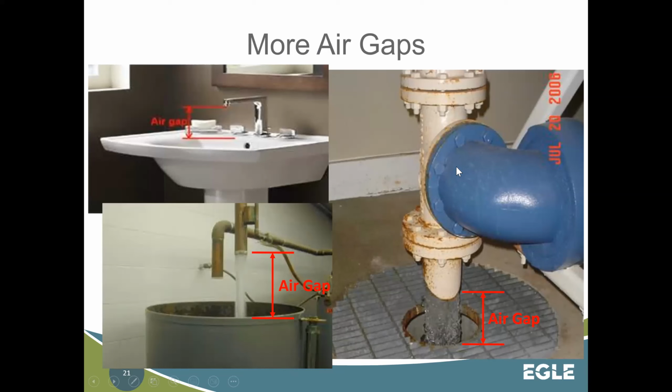And then here's an air gap to a drainage basin that you see typically in commercial sinks in commercial kitchens. And you can see that this one's cut at an angle. And we typically recommend, if you can, cut the pipe at an angle, because it doesn't allow the water to create that mushroom effect off the bottom. It breaks the tension of it. It discharges all the water and allows air up into it better.